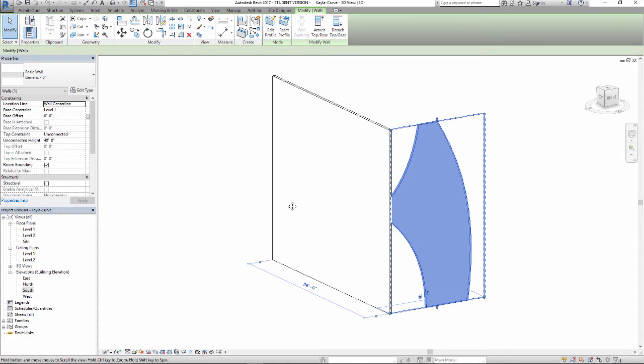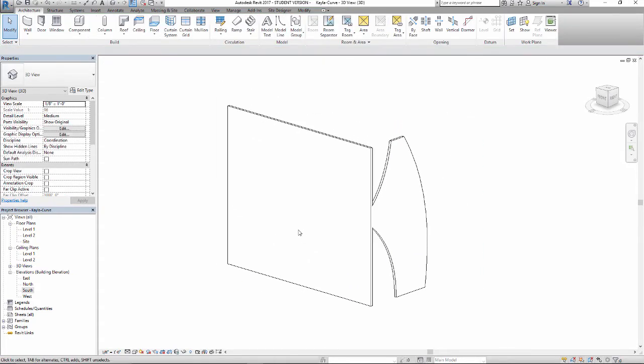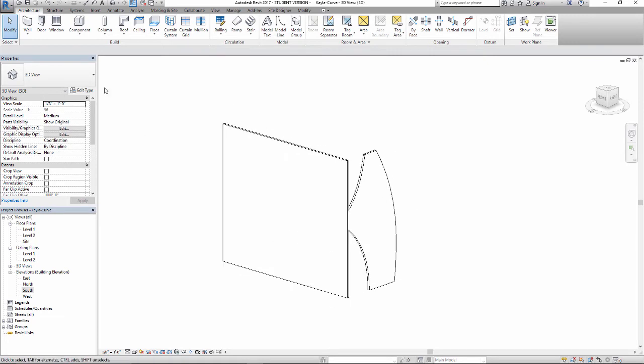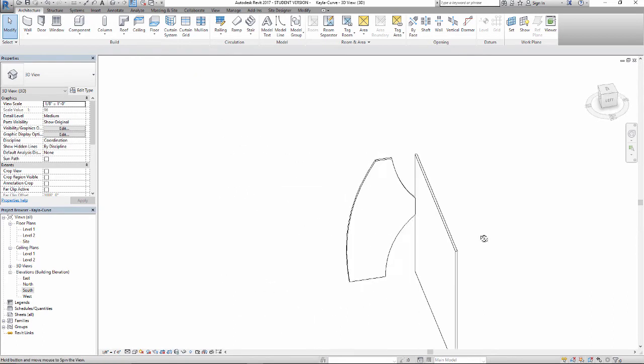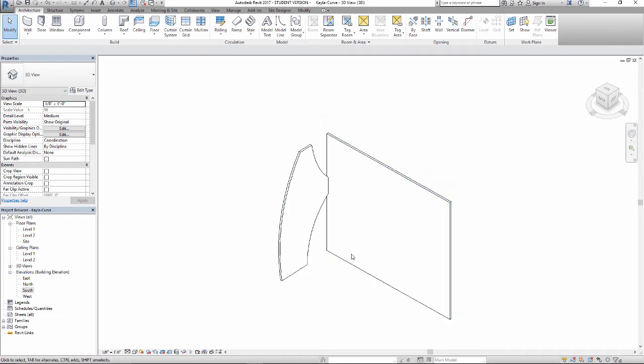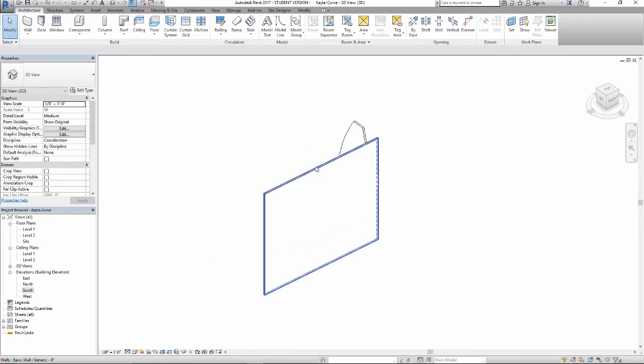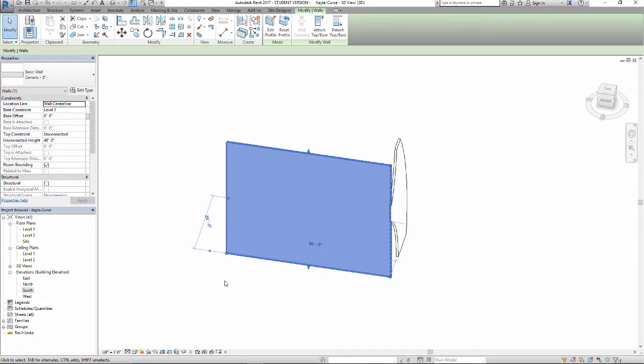So to build a wall like that, there's really not a wall tool that we can use to start bending and bowing the wall shapes. We need to go into the massing tools. And we need to go a little bit further than that as well, because if we want the wall to curve to the inside and not just conform to whatever the shape outside is, we actually need to entirely replace one of these wall elements with a brand new massing object.